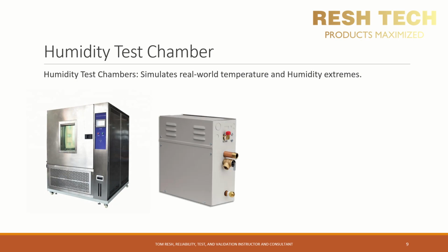To produce the high humidity levels, chamber manufacturers add what is called a steam generator. A steam generator typically has an internal heater that generates the steam or water vapor, which is pushed into the chamber using forced air. A steam generator can also use mechanical components and a heater to push the moisture into the chamber as well.